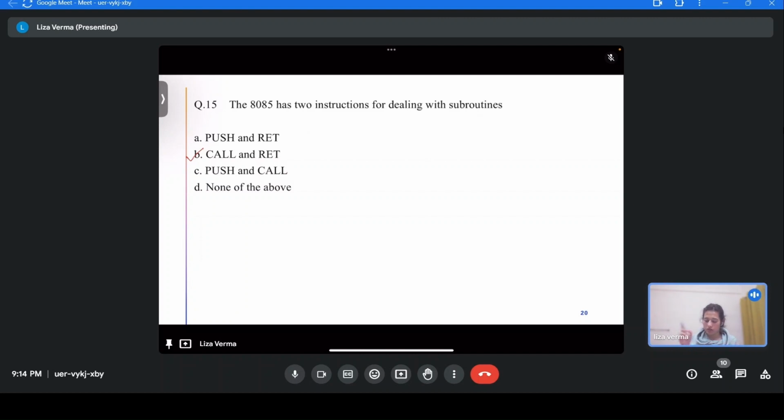Let's say this is the program: MVI C, count. You load some number, which I'm calling count, then you keep decrementing it, and jump if not 0, and the loop goes in here. You know that the loop will be executed the number of times this register is loaded.